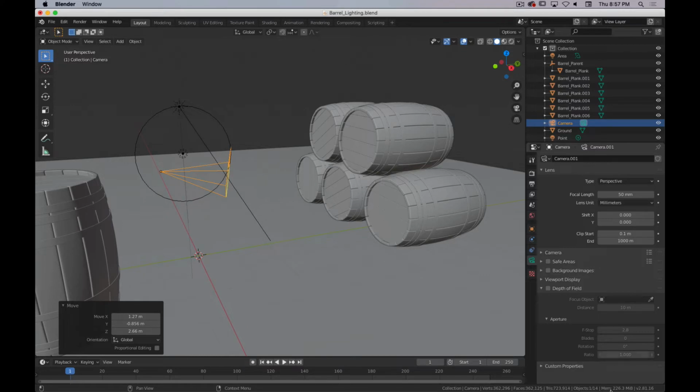So if we look at our camera options, there's definitely more to play with here. And I'm not going to go through all of this right now. I really just want to focus on how to get the camera where you want it to be. And then changing the focal length, so basically zooming, and adding some depth of field, because depth of field is nice and pretty and makes your renders better. So first thing is I've got a camera in our scene. How do we look at it?